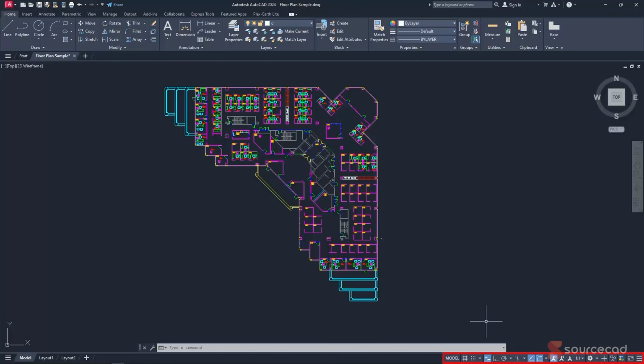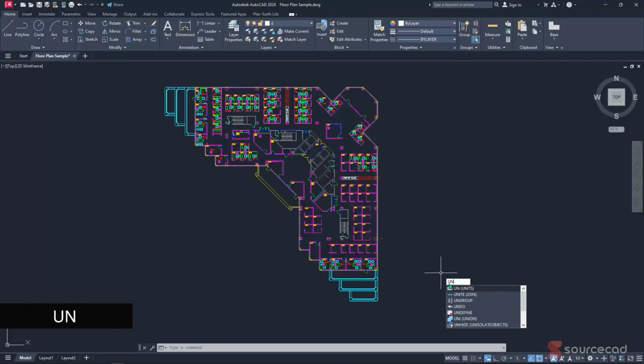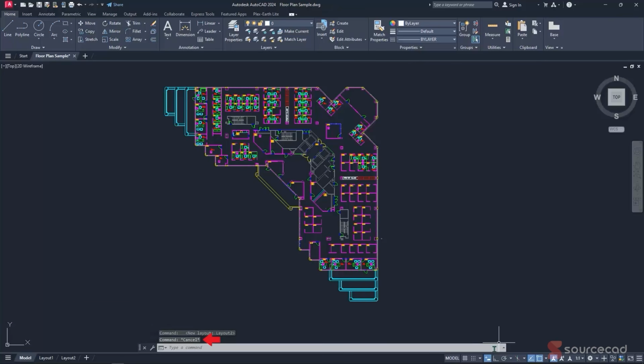At the bottom right hand corner, we'll find more options. So over here, we have options such as dynamic input, which simply means if I was to input a command, let's say units, which is UN, my command will be floating within the drawing. Let's say I hit escape to cancel the command and you can simply see it here. If I turn it off and I try to input the same command, for this case UN, you'll actually see that it will be entered within the command line. So that is actually the main use of the dynamic input.